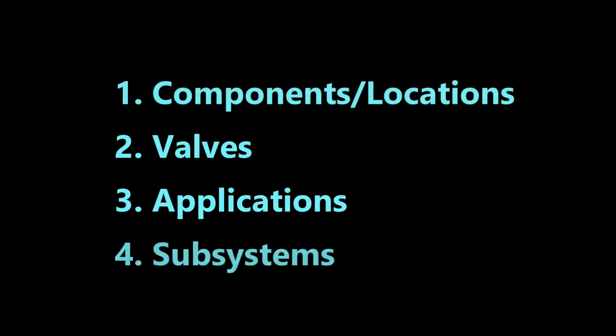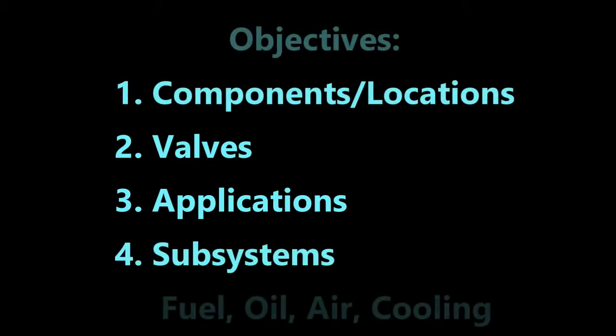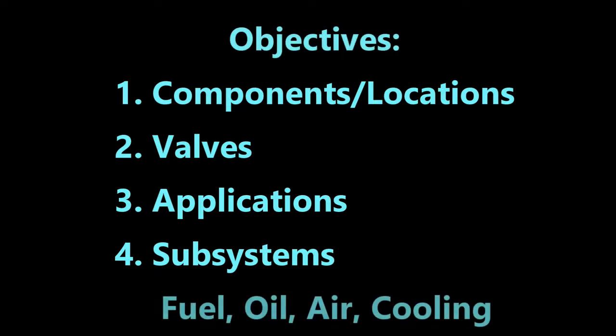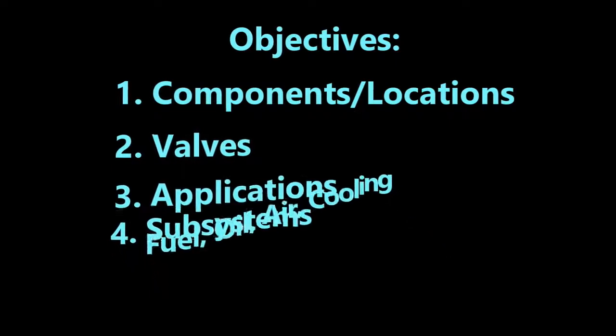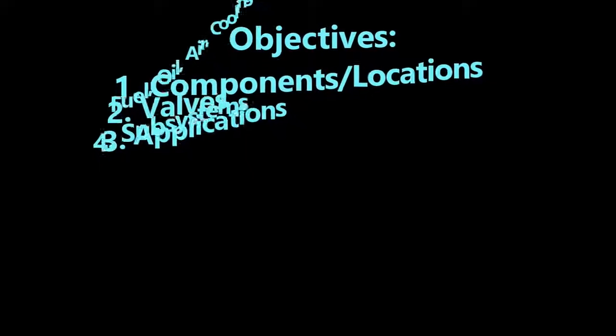And also know that the applications for the APU are basically so that you have a source of power on the ground. Of course, you have that in flight, and pilots have that available in case they need a backup. They have that APU. Now on the ground for maintenance, if, for example, you don't have power at the facility, you can always get the APU going, which, by the way, is started by a DC volt battery.